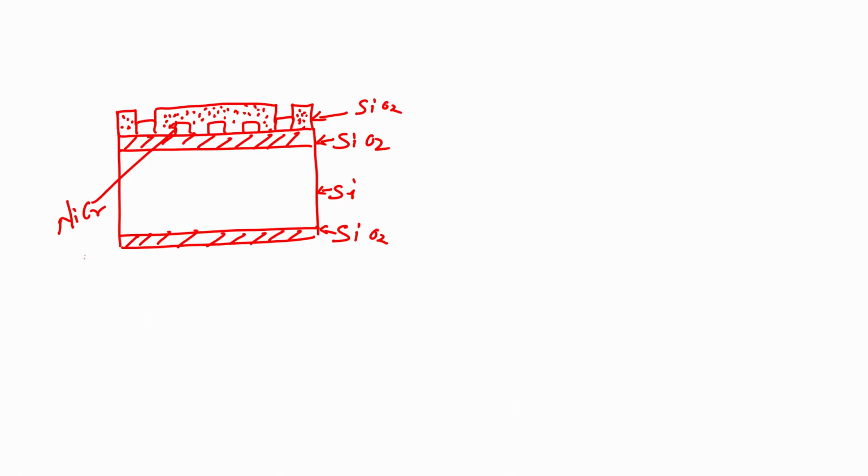So, this is nichrome, a heater. Silicon dioxide with which technique? PECVD. Silicon dioxide with which technique? Thermal oxidation. Silicon wafer is there, and then this is nichrome using PVD, and then we pattern using photolithography. Over that you have interdigital electrodes like this, which are made up of chrome gold. Let us design it like this, and then over this you have the piezoresistive material.